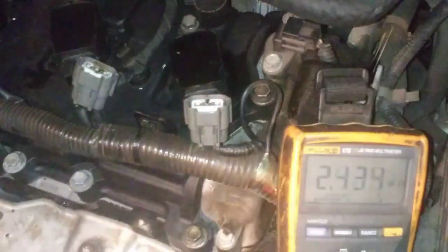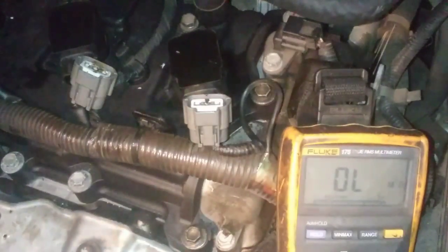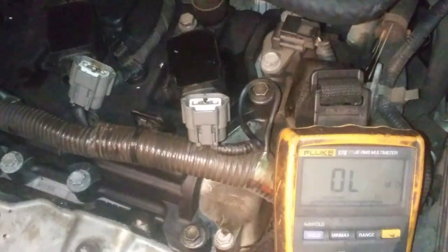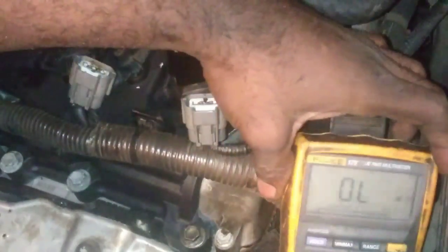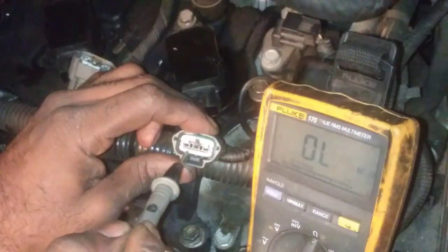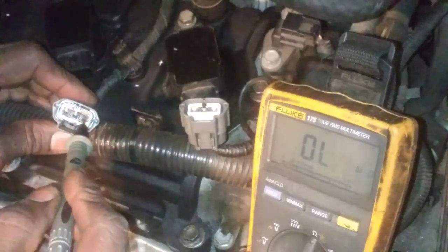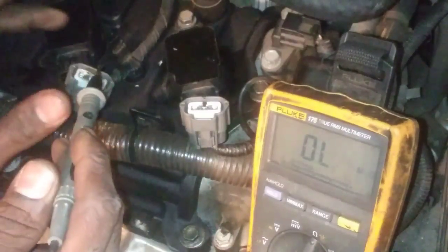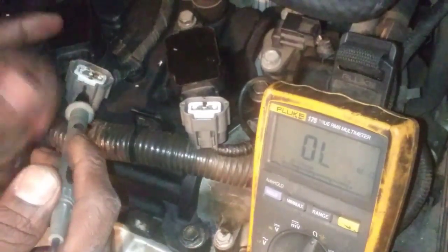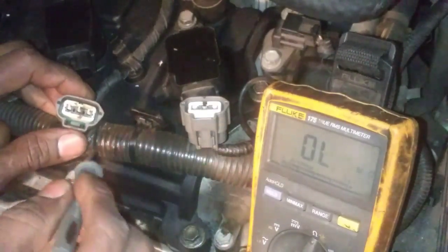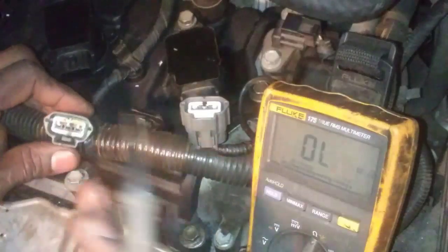Alright, I just got back off my test drive here, and I just want to do a quick resistance test before I say this car is done. I think we got this. There we go. Get that glare off. So I'm just going to check the signaling side, because that one was shorting out, causing the coil to burn out. And I'm going to have to replace one of the new coils, because I did put that in place of one of these coils, and it wound up having a little bit of an issue when I was looking at some data. But I'm going to replace that under warranty, and they'll be perfectly fine.